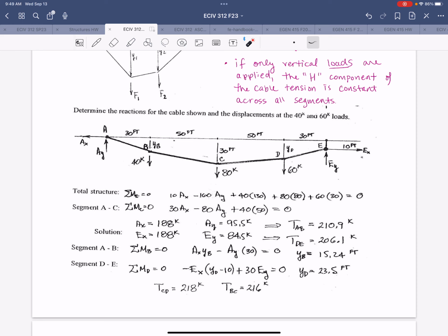And another thing I want to point out too, right? If you look at the top chord, what's something that's different from what we assume in truss analysis? How are the loads applied? They're not at the joints. Right, exactly. It's essentially a continuous load application, right? But we assume that the loads are only applied at joints in our analysis.